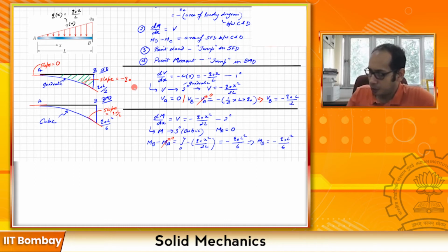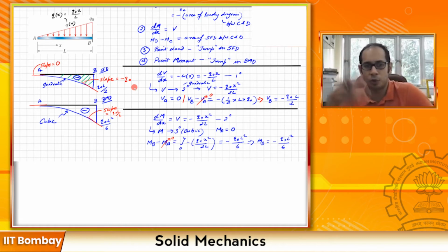Right? And also, as you can see, your bending moment is negative and your shear force is also negative over here. So you have to do more problems to get this into your DNA, how the relationships are and how to use those relationships to get the values of the shear force and the bending moment. So let's compare this with what we got previously in the method of sections. So you see how fast this was. We did not have to write an equation and so on. It was just using the relations we get it.